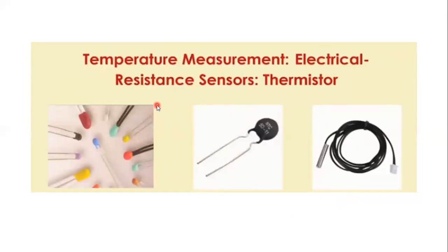And the next one is thermistors. We know that a thermistor is a semiconductor resistance sensor. Thermistors are thermally sensitive variable resistors made of ceramic-like semiconducting material. A thermistor responds negatively to the temperature. I have already told that when temperature increases, the resistance of the semiconductor decreases. That means it responds negatively to the temperature, so it is known as an NTC thermistor.